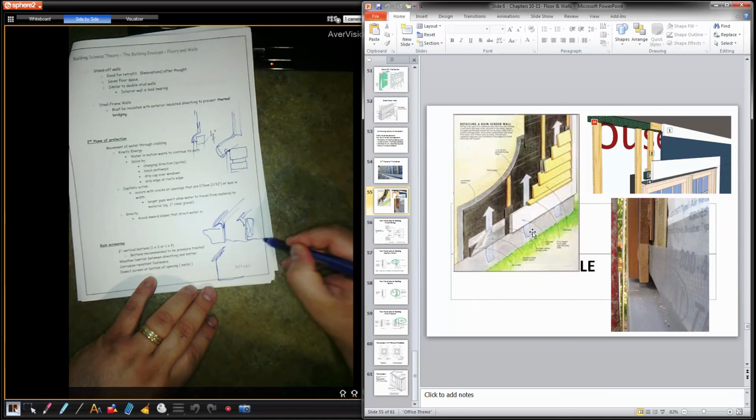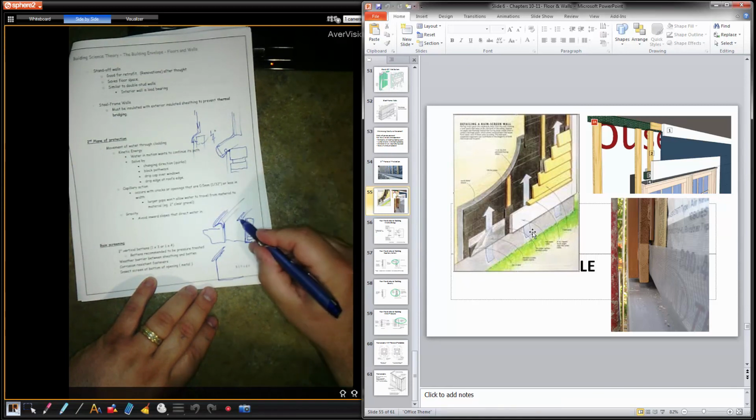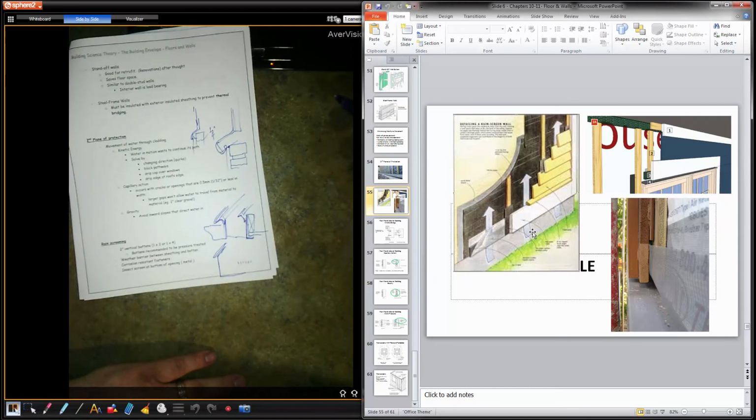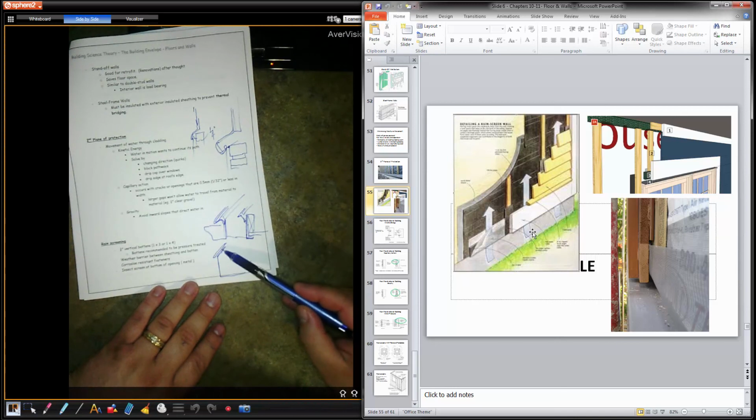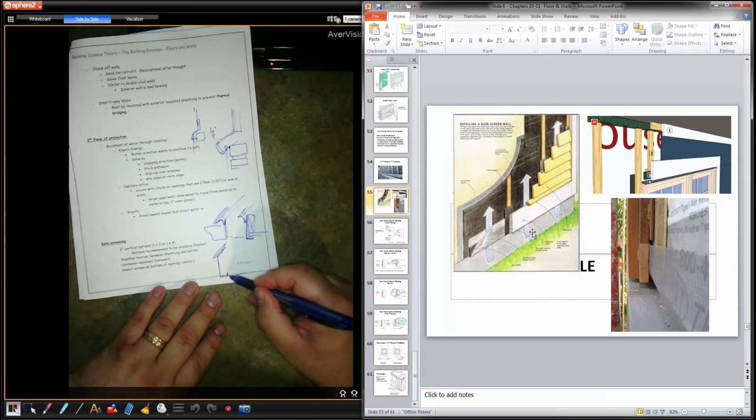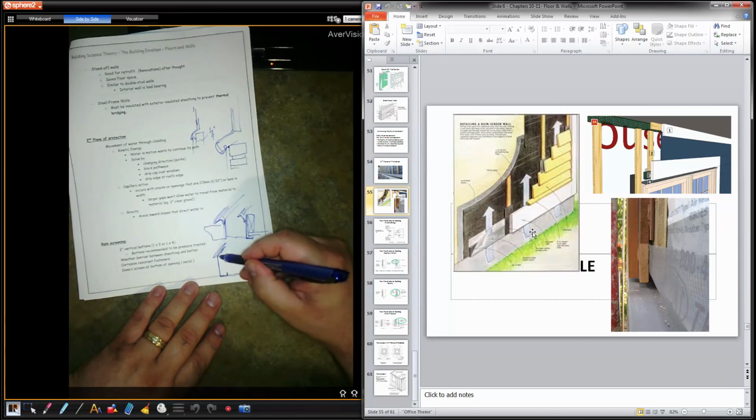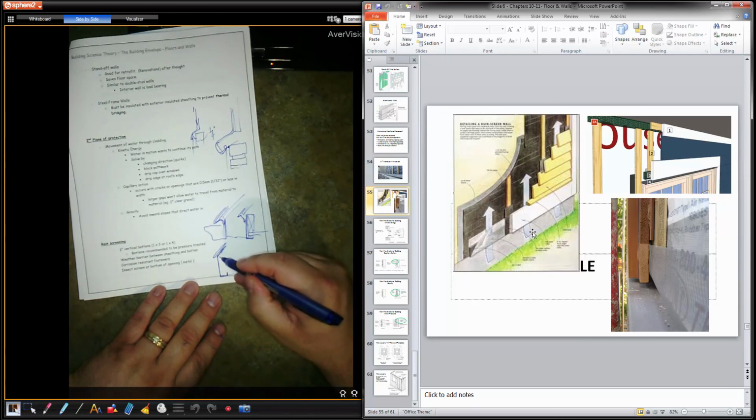And we have soffit put in place, and then fascia board comes below it. So that fascia board here is a finished fascia, is aluminum, very thin. So the top of that fascia is held in place by the drip cap. Okay. Older homes are done this way. So piece of metal bent from here to here to here and follows your roof line. There's your rough fascia.